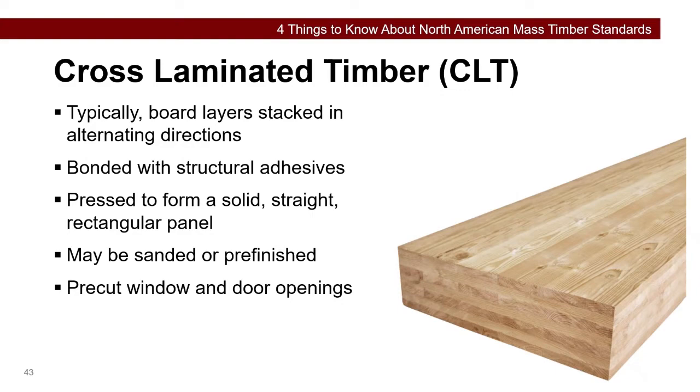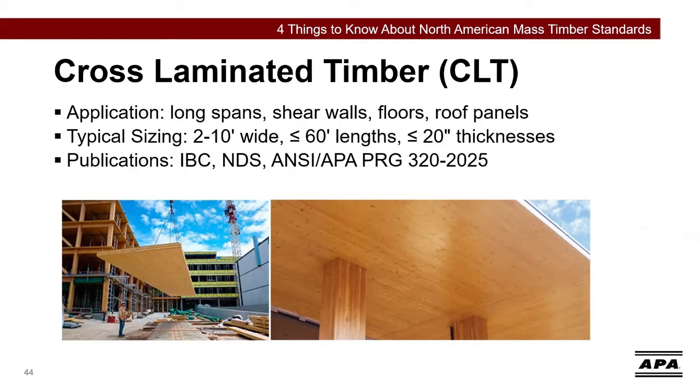The panels can be manufactured at custom dimensions, but check with each manufacturer as transportation restrictions might dictate their size, especially their length. CLT is fast and easy to install, generating almost no waste on site thanks to factory prefabrication. CLT also offers design flexibility and low environmental impacts. It can be locally or regionally sourced.